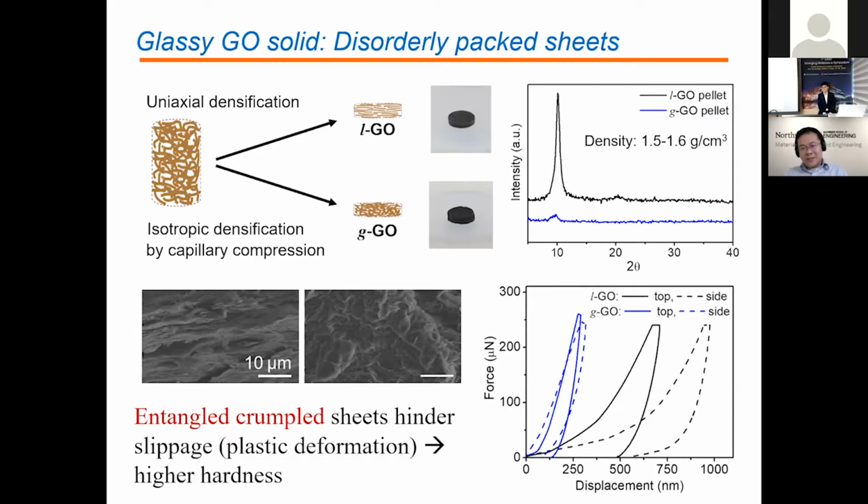But what's most striking is that the hardness now is actually harder than the vertical direction of the lamellar solid. That was a little bit puzzling in the beginning, but then we realized that it's also perfectly reasonable, because the lamellar solid is not really a single crystalline lamellar solid. It is a polycrystalline solid, so when we indent this, we are going to push these nicely stacked domains apart because they're connected by weaker domains.